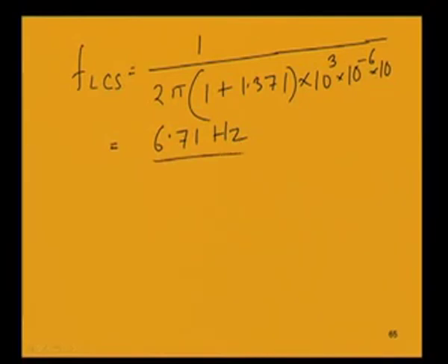So in order to know the lower cutoff frequency due to this capacitance, we have seen that we have to find out the effective resistance by looking from the capacitor, and for finding that out we have to find out the input resistance in the mid band region, and that input resistance is found by considering the small signal model.